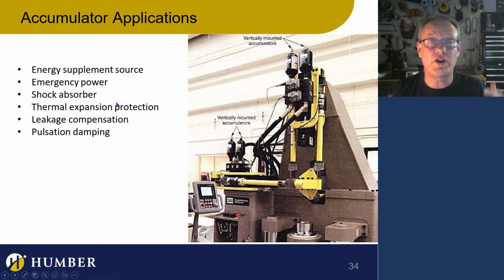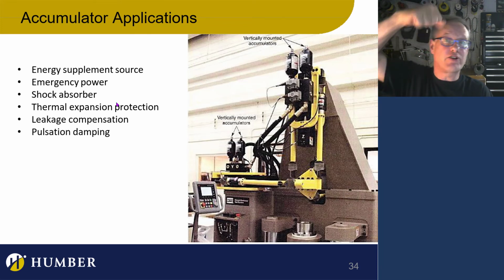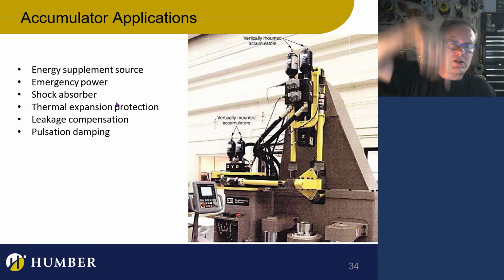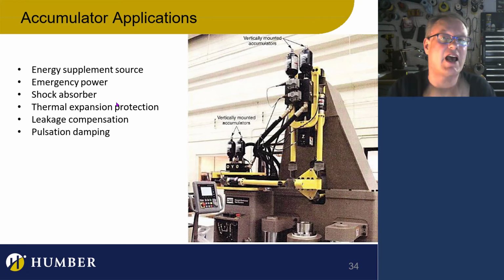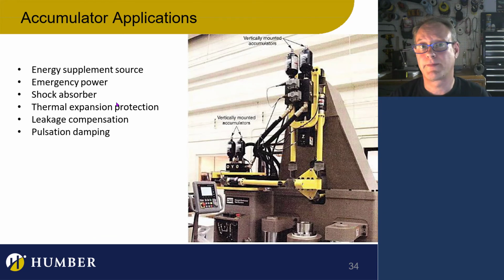Shock absorbers. Oh yeah, for sure. It's like a capacitor in the system that's dealing with electrical surges. It's definitely a very good shock absorber, and you can actually use them as shock absorbers. You can put a hydraulic cylinder somewhere that requires a shock absorber, and you can just hook it straight up to an accumulator. It's pretty cool.